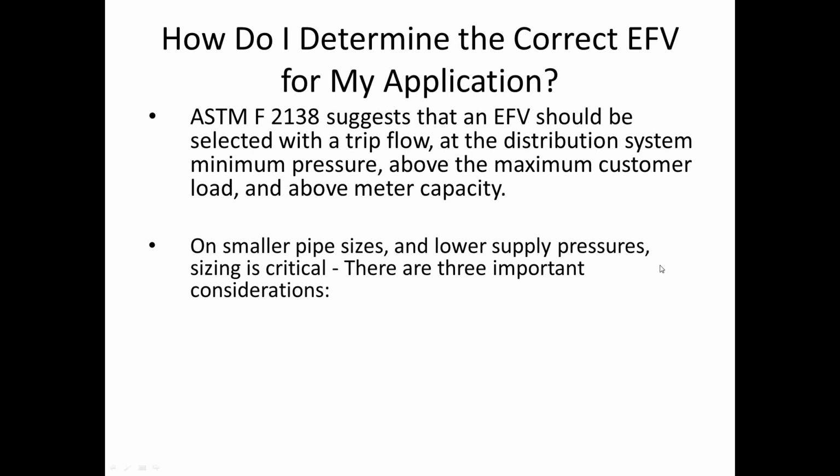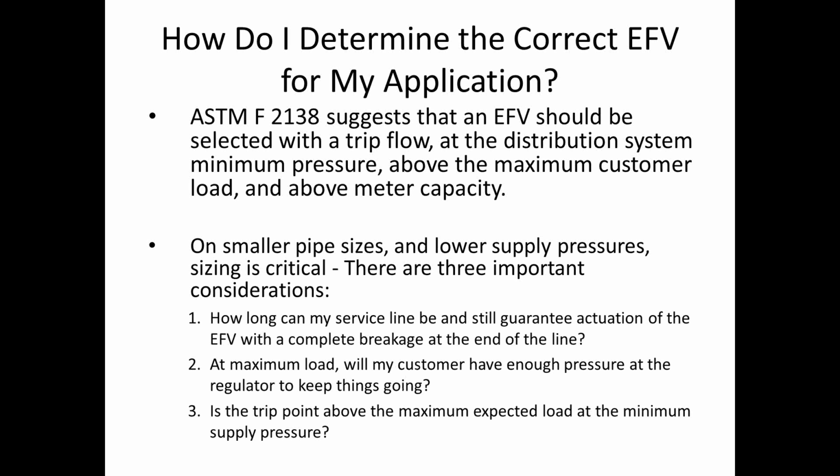On smaller pipe sizes and lower supply pressures, sizing is critical. There are really three important considerations. How long can my service line be and still guarantee the actuation of the EFV with a complete breakage at the end of the line? Meaning, will I cover my entire service line length with this excess flow valve?